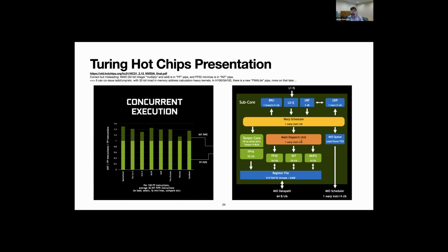But again, you only get 1 warp instruction per clock scheduled. So of the full-speed pipelines like FP32 and INT, you can only use 2 of those pipes at full efficiency. Potentially, you still get bank conflicts and other things that mean you don't get full performance. Like when you think about the speed of light, you'll never get 100% because there are loads of low-level bottlenecks. But depending on the case, the warp scheduler will be the bottleneck.